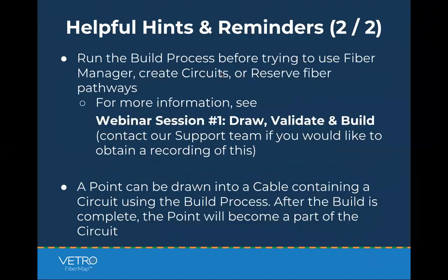Another helpful hint to reiterate this point: run the build process before you try to use FiberManager, before you try to create circuits or reserve fiber pathways. For more information on that, you can learn about draw, validate, and build in our last webinar. Let us know if you want a recording of this. And lastly, a point can be drawn into a cable containing a circuit using the build process. After the build is complete, the point will become a part of the circuit.